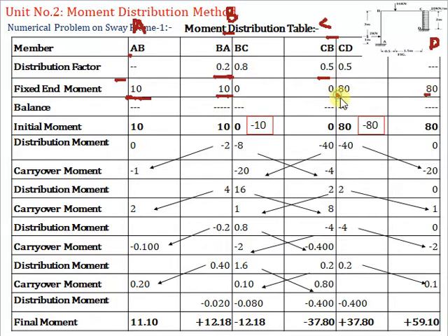So these are the fixed end moments. After treating a column end as fixed, we translate it toward the right-hand side. So these are the fixed end moments for the column. This moment distribution table is only specifically for the column, because we are doing the sway analysis for the column. So put the values related to that column.